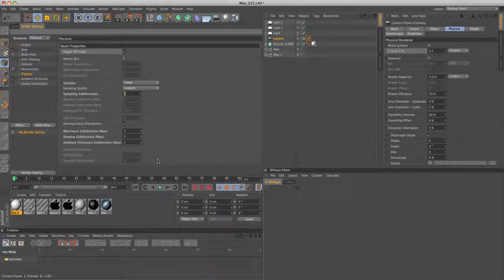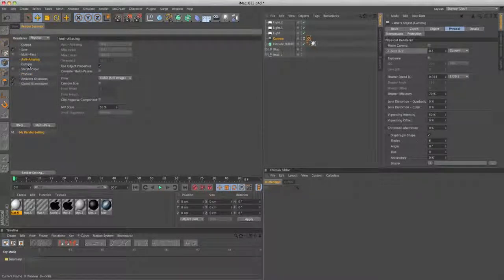So if you wanted to bump this up to, like I said before, the render that I did on my Facebook was 10. So if you bump that up to 10 and see how it goes, and if not, you can always lower it down. And the last thing that I'm going to do is just show you how to render it out to an actual picture. Oh, and there was one thing, if you're using the physical rendering, what I like to do is change the filter under anti-aliasing to Mitchell, and that gives you a really nice sharp anti-aliasing.